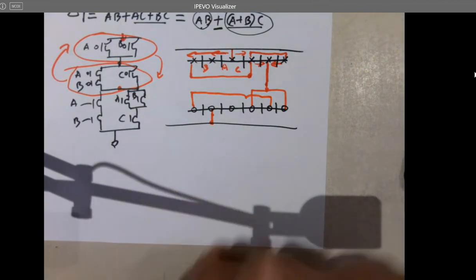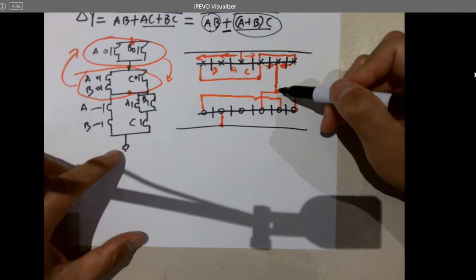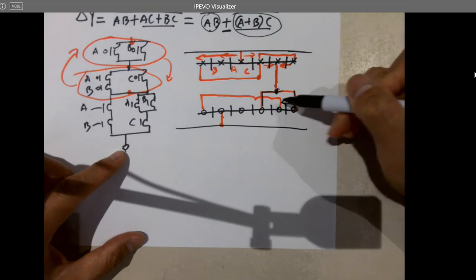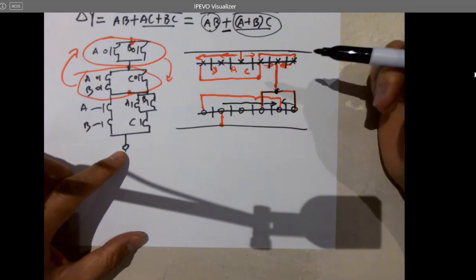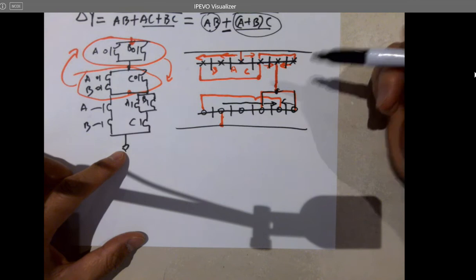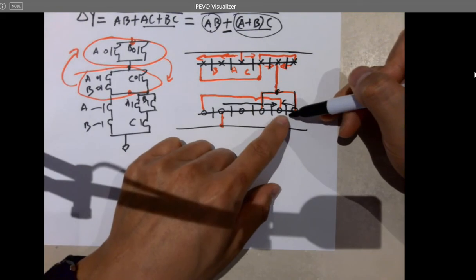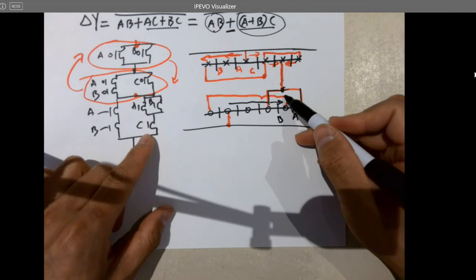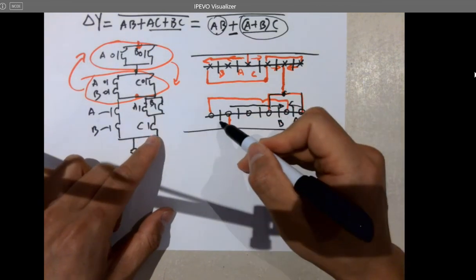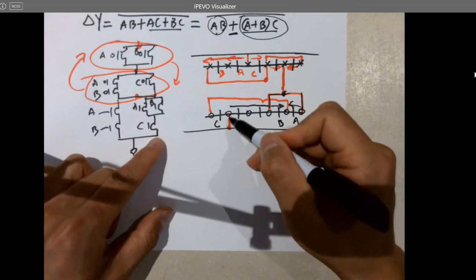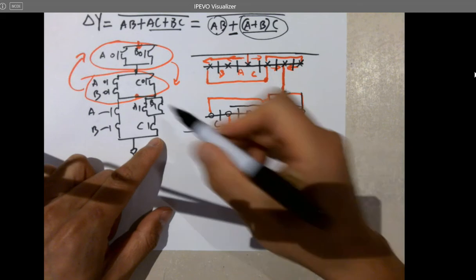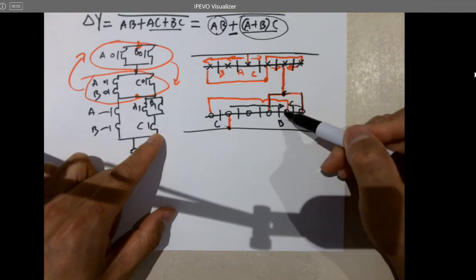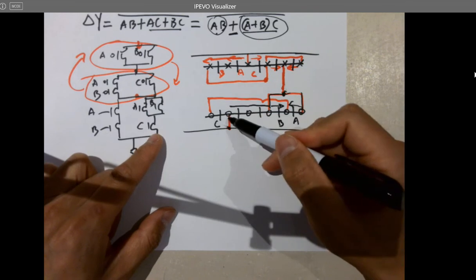Now let's verify it, see if that's correct. Output from the top PMOSes, one line, two lines, so two branches. 1, 2, 3. So these two are in parallel, so these two will be A and B, right? And merged to one point. And so what is this? Yeah. And then go to the ground. No problem here. So what about the other branch? So we just went through this guy, right? So here, A, B merged. Back to C. And go to the ground.